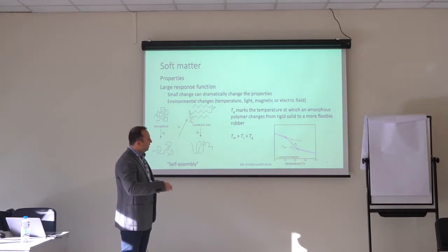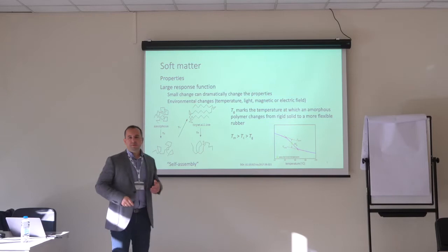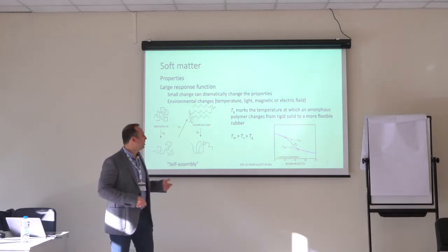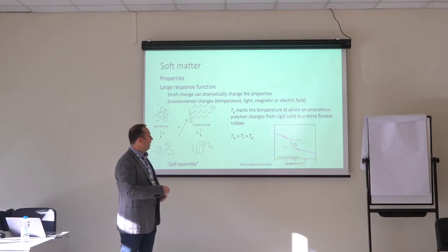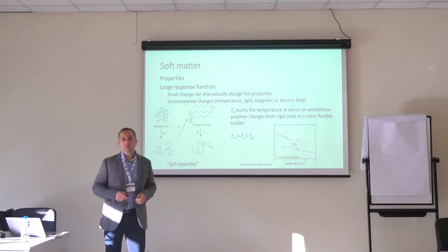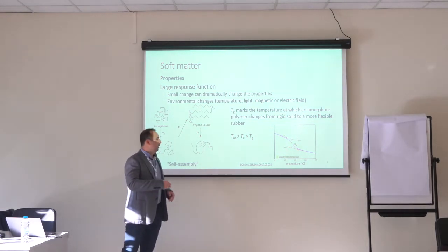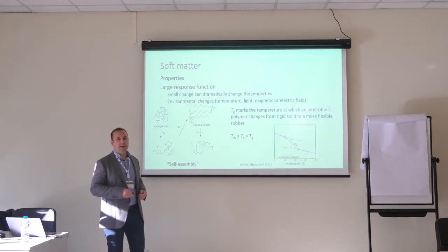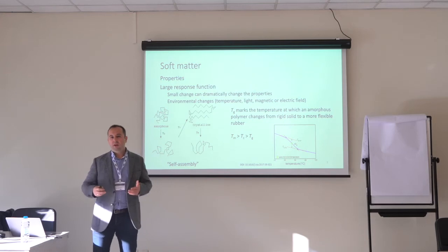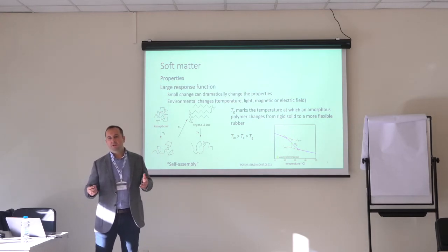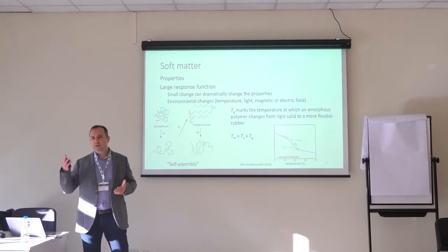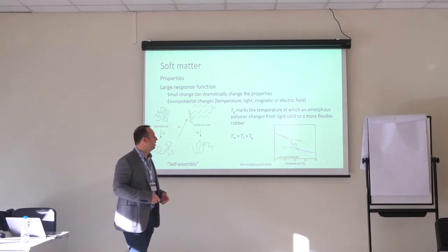Here, what you see is how you define a glass transition temperature, both experimentally and computationally. I didn't put a specific label on the vertical axis because, in this case, it might be a property that decreases when you increase the temperature. For example, when you increase the temperature, most systems have an enlarged volume, and if you increase the volume, you end up with decreased density.